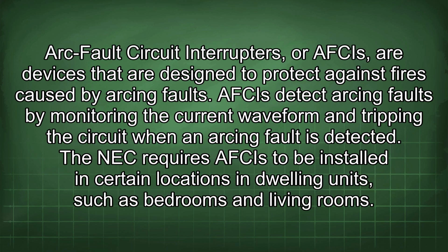Arc fault circuit interrupters, or AFCIs, are devices that are designed to protect against fires caused by arcing faults. AFCIs detect arcing faults by monitoring the current waveform and tripping the circuit when an arcing fault is detected. The NEC requires AFCIs to be installed in certain locations in dwelling units, such as bedrooms and living rooms.